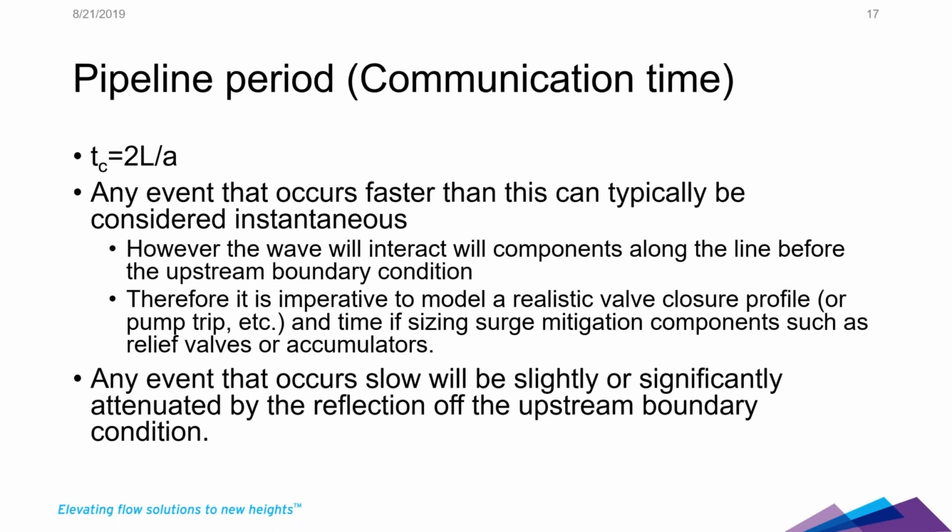And then after you've done that, look at the flow and pressure rise change at the valve. If you have a very large valve, a full bore ball valve, a full bore gate valve that is the size of the line, it's not really going to restrict the flow until the final few percentages of closure. So you might still have, in effect, an instantaneous closure. That's going to be really important. If you want to learn more about ball valves, gate valves, inherent characteristics, check out my other webinar about the importance of inherent valve characteristics in waterhammer analysis. I gave that maybe a month ago or so. Look in our archive, it's a good webinar.